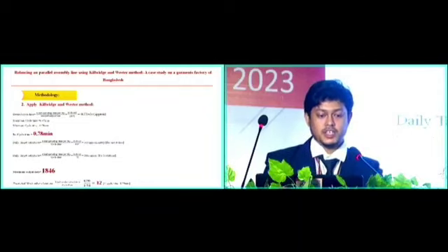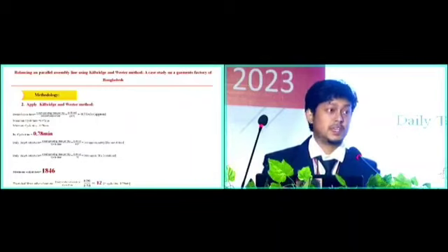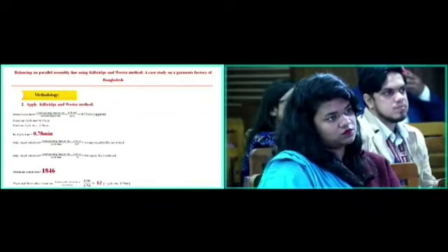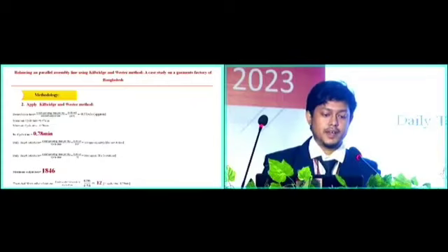We calculated desired cycle time equal to total operating time per day divided by desired output rate, equal to 0.77 minute. Maximum cycle time equal to 8.97 minutes, which is calculated from the OBS report of our factory. And minimum cycle time, we found 0.78 minutes. So cycle time will be 0.78 minutes.